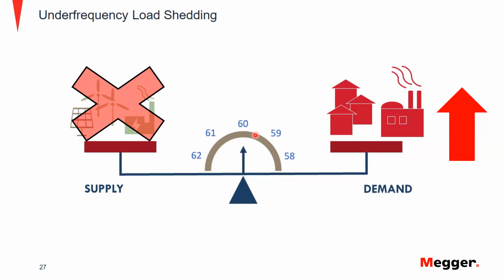We open the connecting breaker out in the substation. It connects us to the grid. We become unsynchronized to the grid. And then now our generator breaker is opening, and then we have to get everything back up to where it was. But even at that point, we can't do that because we still got to shed some of the demand. We need to make this demand smaller.